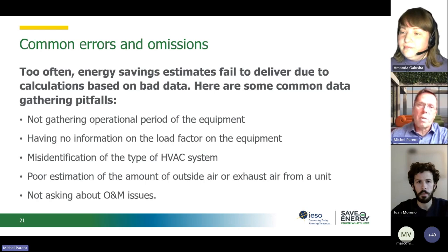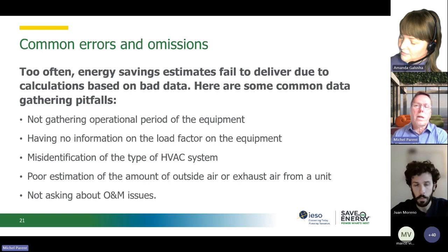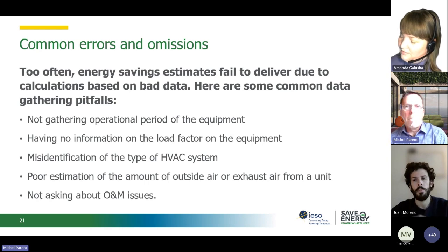If you do have the mixed air temperature and you've got the return and outside air, you will be able to correlate that percentage of opening of your dampers to the actual outside air. Like I said, it has to be cold enough to use that equation. It's easy to put in Excel, and then you get your monitoring data. So just be careful about that.